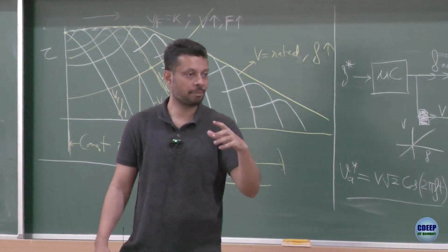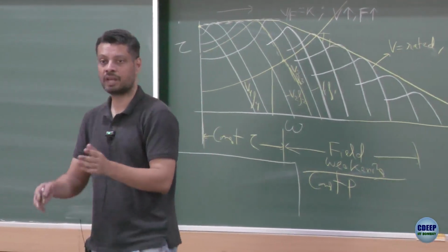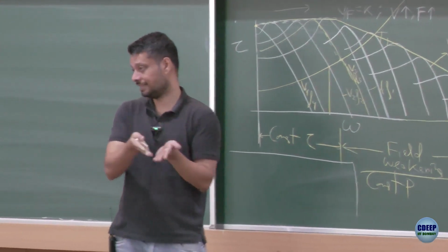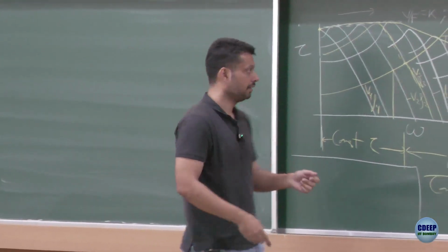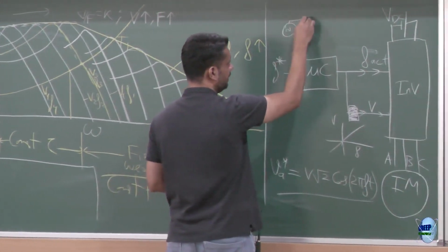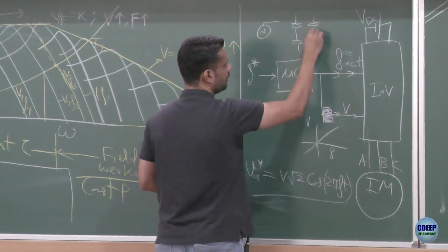Rectification, right? You had an AC supply, you would plug it into a single phase AC supply and you would have a full bridge rectifier, and that full bridge rectifier will rectify the AC supply and give you a DC voltage, right?